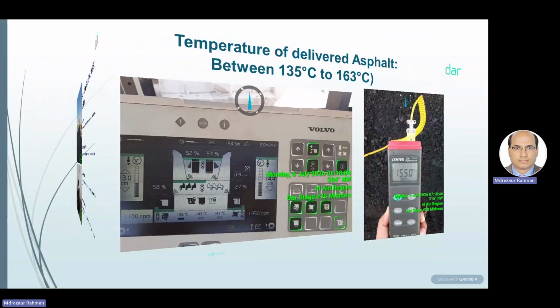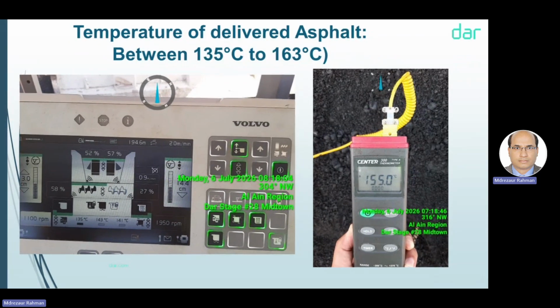Okay, now I'm going to show you the screenshot. This is a paver. In terms of what you asked, this is 2 meters per minute. It is used between 2 to 4.8, but at site we have to maintain very slow, and it should not increase the speed. Same speed we have to go. So this is 2 meters per minute. The paver should move very slowly. And if you see this height, this is for another site. This is 14.4 centimeters. Okay, so this is auto level. From our side, it will be different.